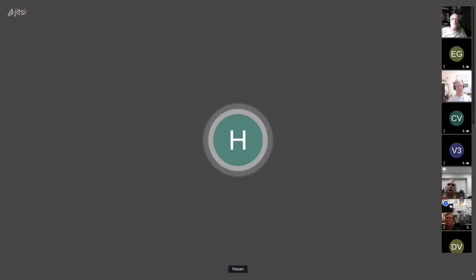Yeah. One more option is there's these Hall effect sensors you can buy, which have like 0.2 milliohms of insertion loss, and they'll actually sense the output current, and it goes up to like 20, 30, 100 amps. The only problem is it has a minimum current of like 2 amps. Yeah. But for high power supplies, that could work pretty well. And some of them have digital outputs, so you could just stick it to an Arduino and have a simple loop. Yeah, I think that's what they use in VFDs to sense the 3-phase currents or the DC bus currents, right? Where we're talking dozens or hundreds of amps.